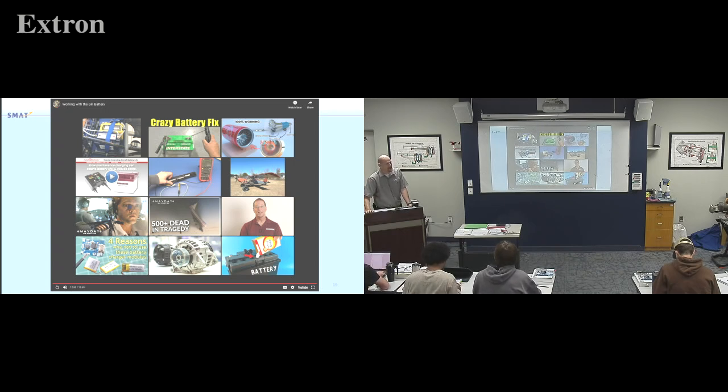So, more common is, we have APUs you'll learn about, a little turbine that's making power. So more common is instead of these honking big batteries, we'll just get an APU to run and provide the power. So use something to start our APU in the aircraft, or maybe a small battery to start an APU. Lead acid to start the APU, and then the APU essentially acts as, you don't need a battery anymore, because it can adjust. It's an expensive pony motor. I believe safety-wise, that's cheaper than having honking lithium ion, or hauling around a bunch of lead. They just say, we'll make our own power.